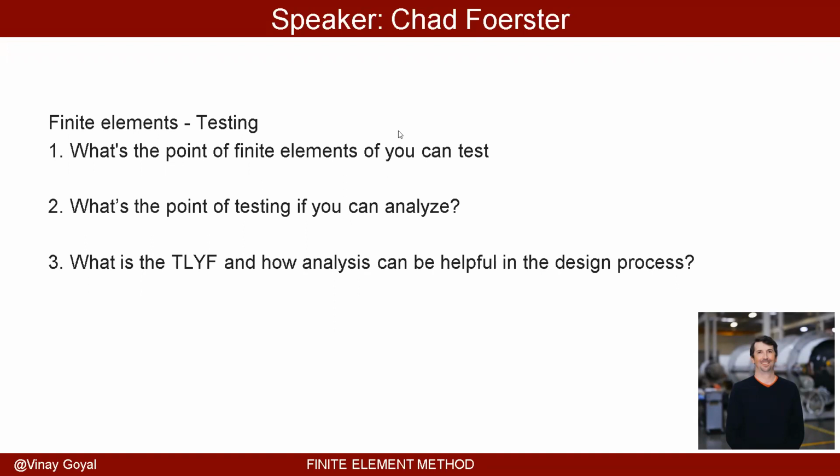The testing, you can do that, but you have to really dig deep and super optimize the test layout. I don't know if anyone's ever done strain gauging, but it's pretty laborious. And if you want a good test, you're going to have a bunch of strain gauges on there. And you're probably going to have other gauges too for measuring position, and you might even have some speckle patterns and do video deflection monitoring, fancy stuff like that. It gets pretty busy pretty quickly.